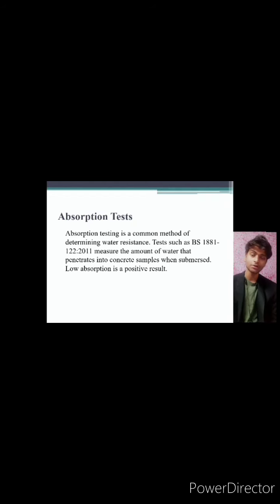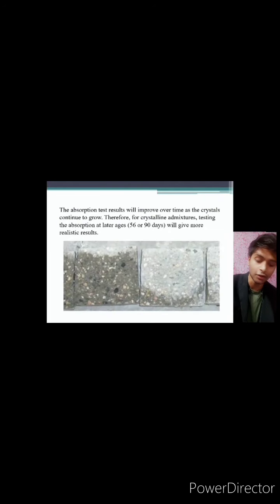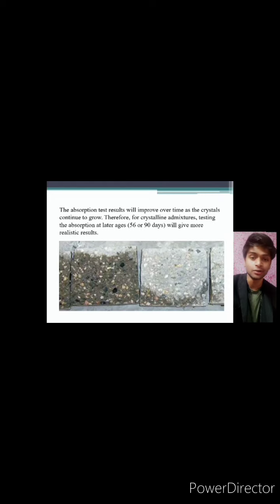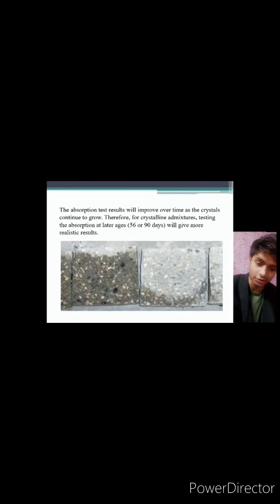The absorption test is a method which determines the water resistance, meaning how much water can penetrate into the concrete sample when it is submerged in water. Low permeability should be the best result. Here you can see some pictures of concrete submerged in water for an absorption test.